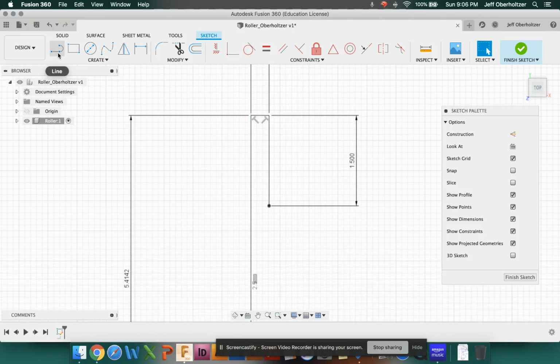And then I'm going to draw another line that's going over to the right. Notice that right now I'm on this extension line. That's why it gets frustrating in this program sometimes. I'm going to come out here 0.6875 inches, enter, and there's a line in there. You can see it. All right.